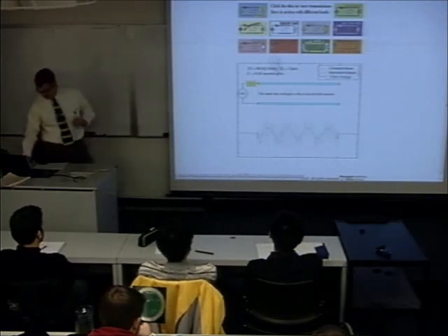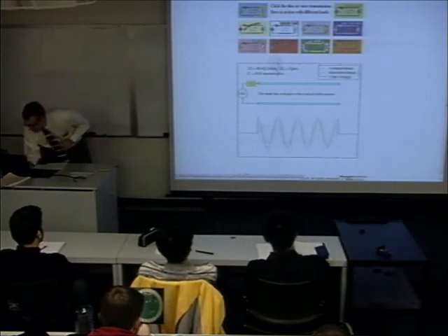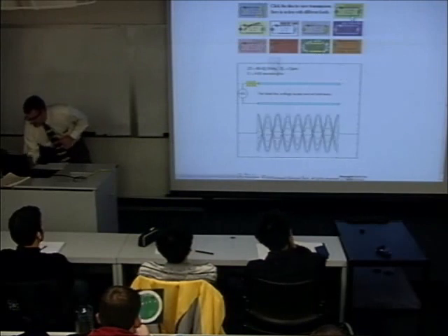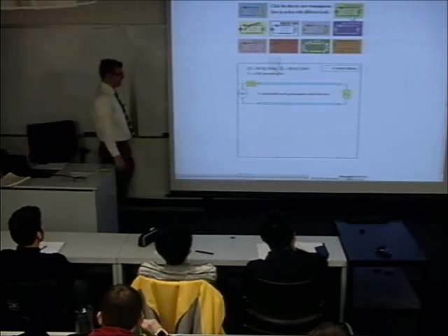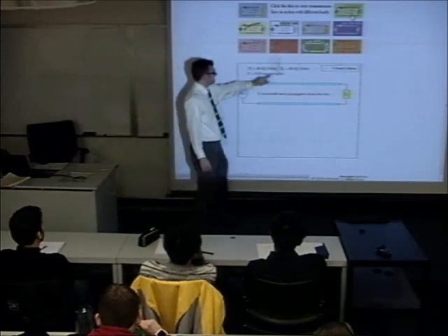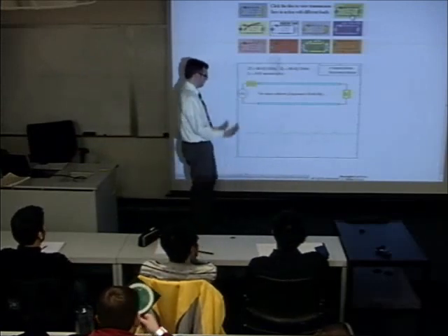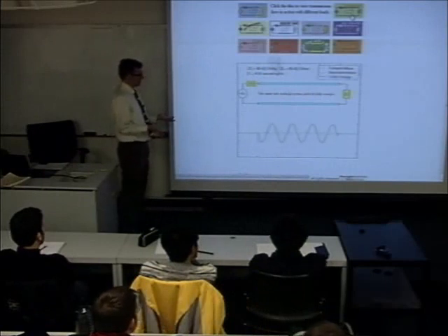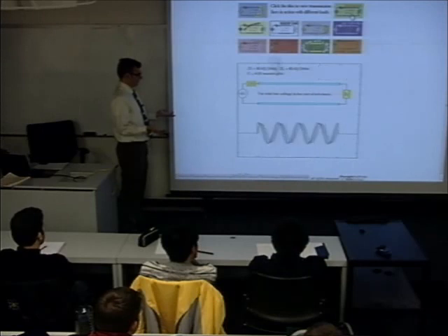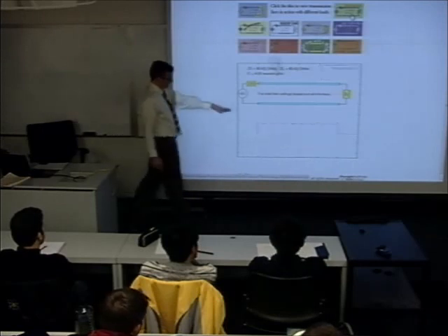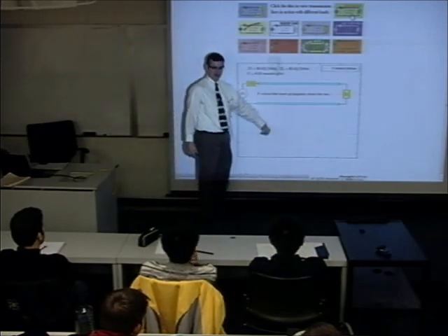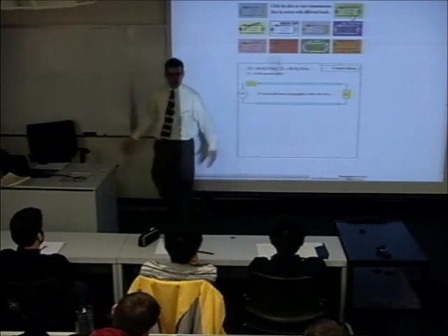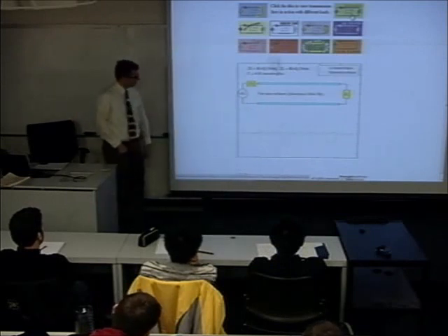Okay. Let's see. What about a slight mismatch? In this case, we've got a 60 ohm load, a very small reflection coefficient. And you see, that's still enough to make a visible voltage standing wave ratio. There's a wiggling total voltage, and the envelope has a VSWR. See, Vmax is a little bit more than Vmin. It'll be like a 1.2 type VSWR, something around there.